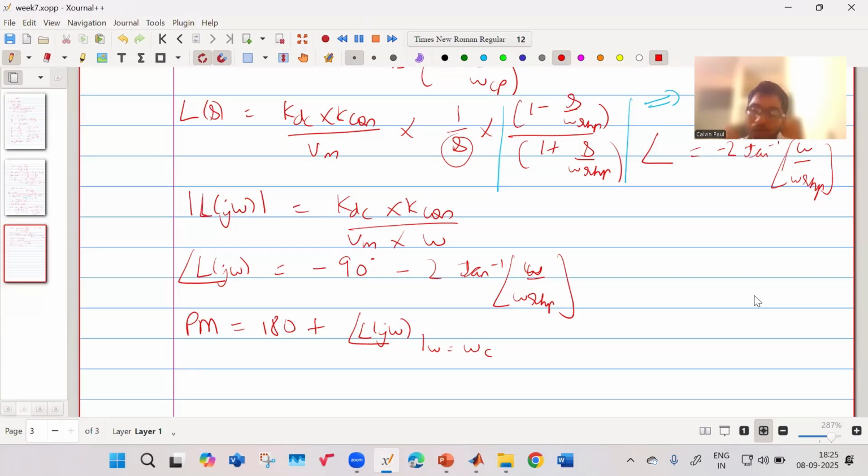So it is like the degree of phase lag which you can still provide in your system so that it maintains stability. So if you want it to be stable, you have to have a higher phase margin. And in your practical system, when you implement it, delays will come. Delay will not affect your gain plot; delay will affect your phase plot. To anticipate that delay, and since your sensors also may have phase lag, you have to have a good amount of phase margin. Usually they select 60 degrees, 45 degrees, etc.